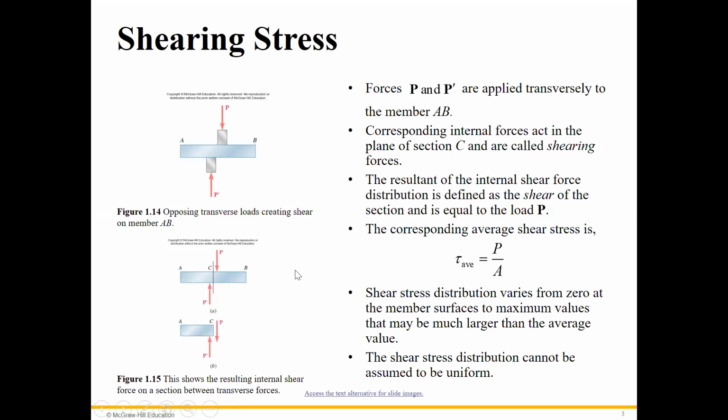Don't memorize something like this. We have these 2 forces and the shear force is equal to this one. The reality is we should first make a section at point C, and then write the summation of forces in the direction of y and find that. The textbook just focuses on the mechanics of materials. It skips the previous steps of writing the equilibrium and finding the internal force.